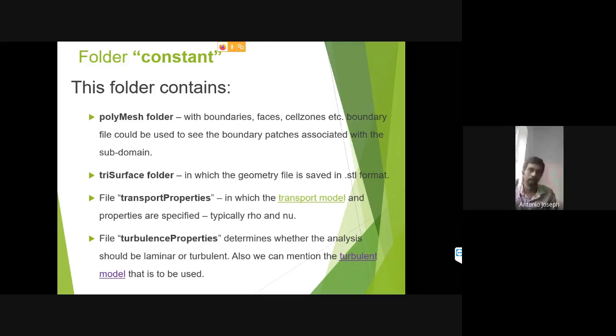The default names for blockMesh are minX, maxX, minY, maxY, minZ, and maxZ, correspondingly the minimum and maximum faces in those directions. In addition to that, we will have the other patches, like the pipe, inlet, and outlet. All these will be named in order, and the total count will be given there.